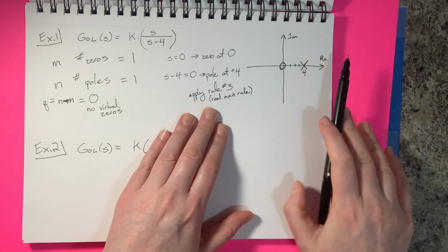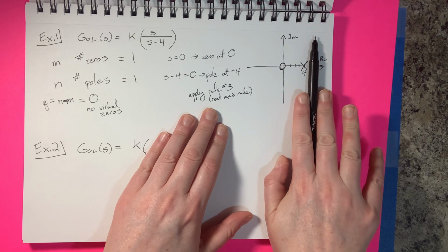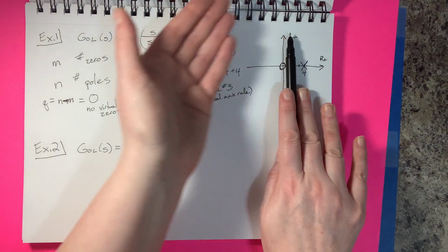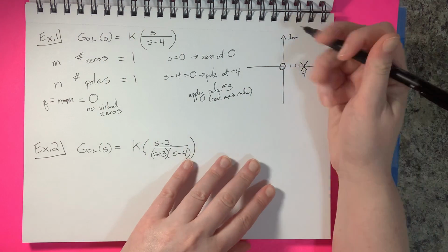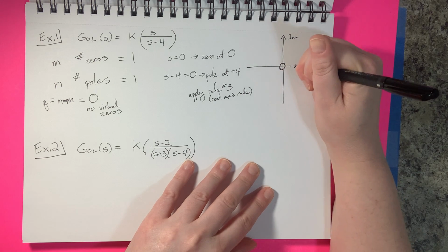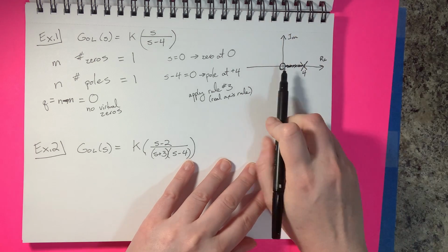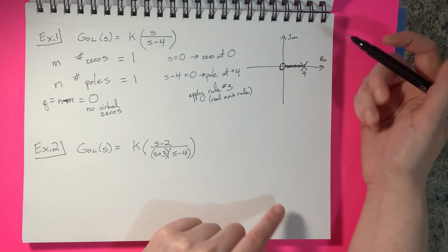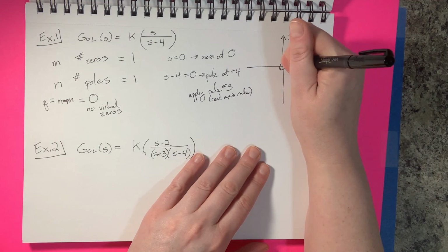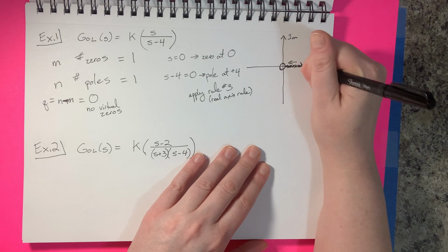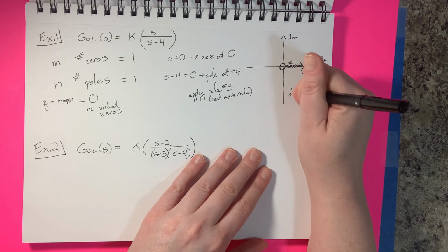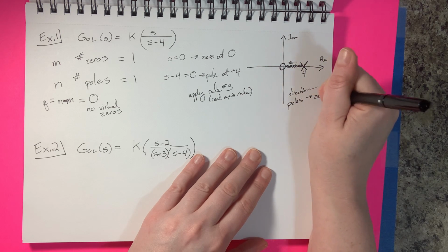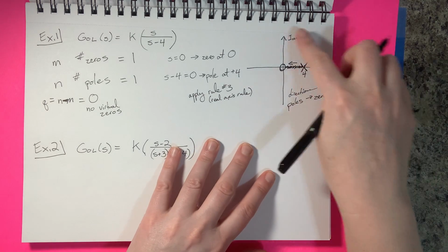Okay, so we'll move our pen across here, and it is 0, even, even, even, and then we pass this first pole, and it is odd, because if we look rightward, we have 1 element passed there. Okay, so we can continue filling this in on the real axis until it becomes even, which it does once we pass this zero. Okay, so that's our migration path. Now we always want to indicate the direction poles move towards zeros. Okay, now this is our completed locus.